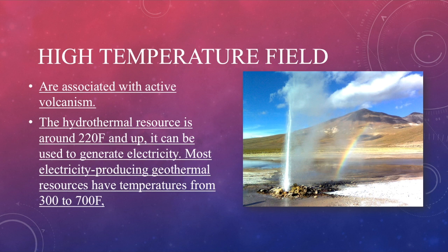High temperature areas are located within the active volcanic zones. They are mostly on high ground. The rocks are geologically very young and permeable. The groundwater table in the high temperature areas is generally really deep. The boiling point of water depends on the hydrostatic pressure. As the pressure increases with the depth, the temperature needed for the water to boil rises along a curve that is called the boiling point curve.